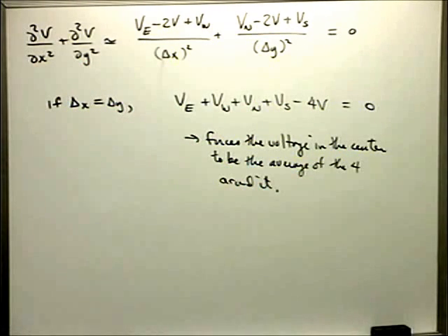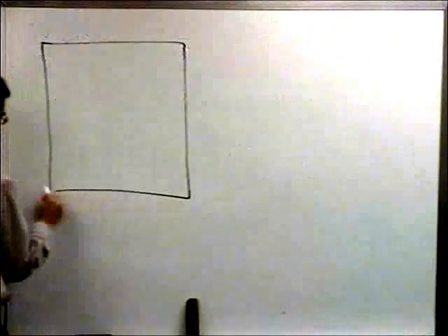You can copy that equation all over the place, put in hard numbers around the boundaries somewhere, and then the spreadsheet will just iterate until this converges to the final values. Okay, so that's an easy way to do it if you're sticking with rectangular boundaries or something. All right, and of course the effect of this is to kind of average things out.